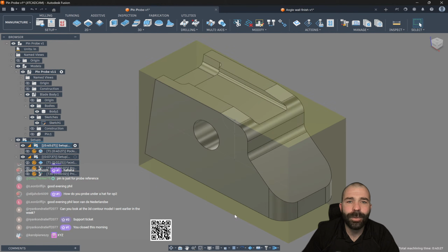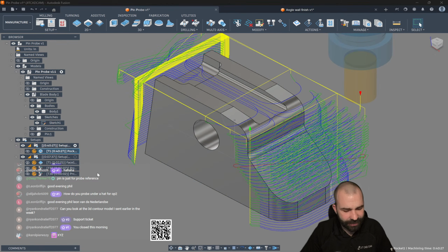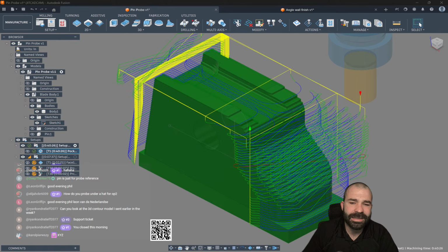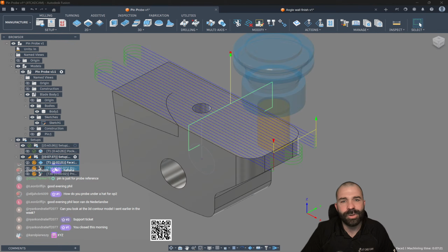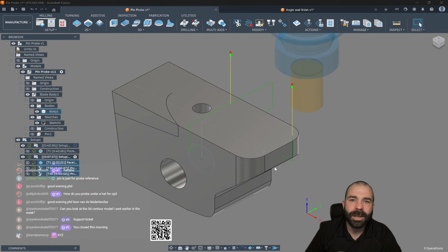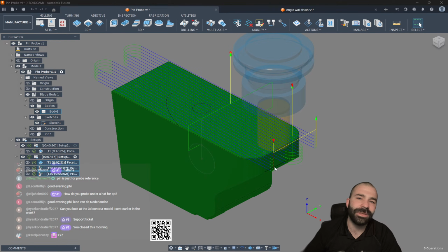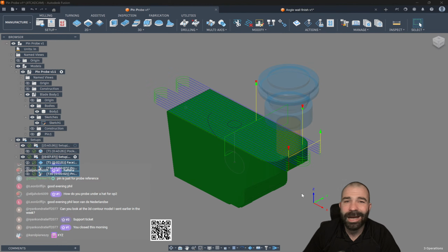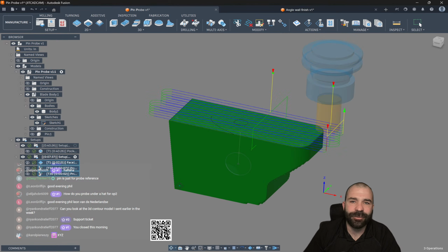So again, now when this sets in on my parallels, everything works nice and pretty. We're against our stop over here to the right. And then we flip our part over. Again, yes, you're going to need a stop a little higher up for this particular part. But what you're noticing is I'm using both of those locations to my advantage, right? Again, minimizing how much work I got to do at the machine and maximizing what I can do inside of Fusion. So just like that, we've now faced it off.